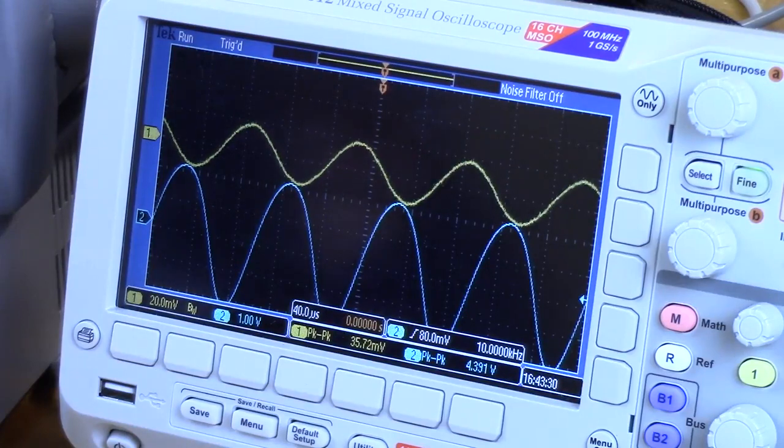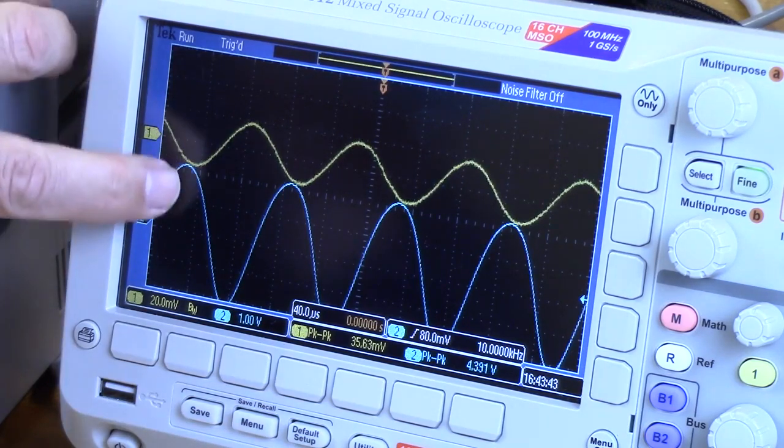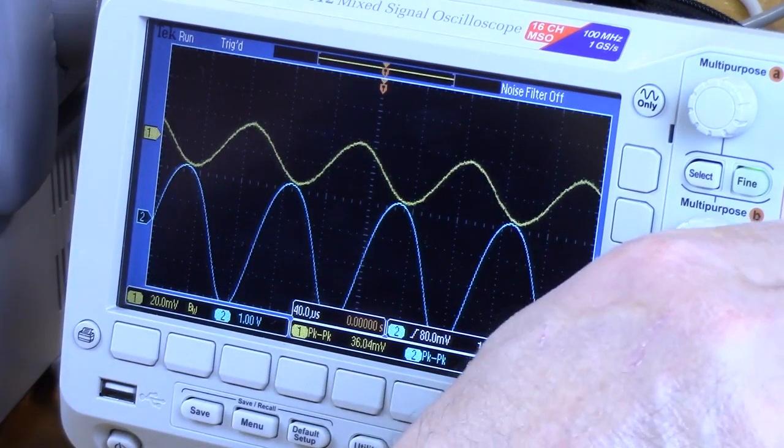We still have a little bit of phase shift in there. We're not perfectly in midband, but 10 kilohertz is probably about as high as I'd like to go. So we're not quite in midband. This is something you could write about in your report, saying that we are not perfectly inverting here. We have a little bit of phase shift, but our measurements still should be okay. All right, so let's slide this back up.